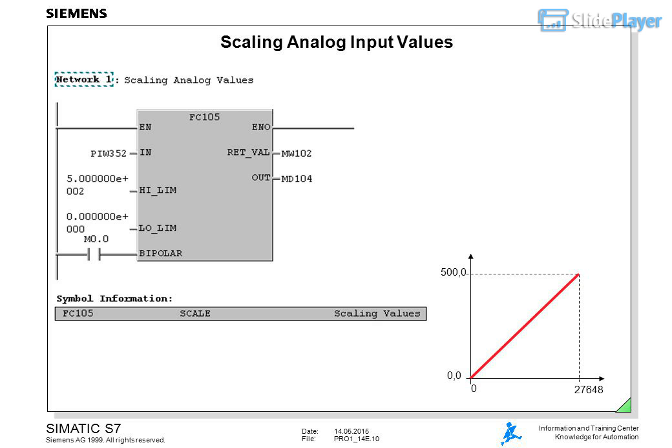Example: the level in a tank is to be measured in liters. The measuring transformer was chosen in such a way that 500 liters have an analog value of 10 V. Scaling: the analog module encodes the analog value 10 V as the integer value 27,648. This value now has to be converted to the physical quantity liters. This is known as scaling the analog value.